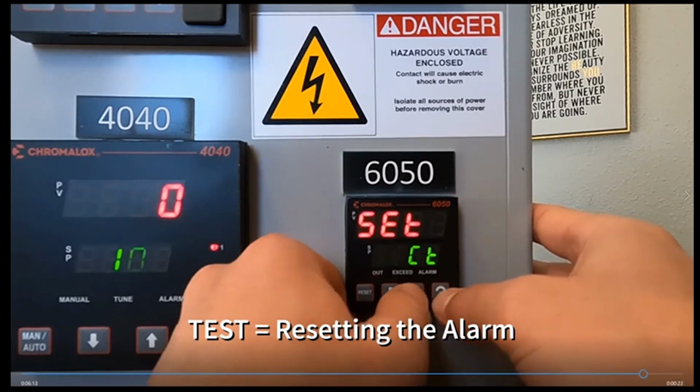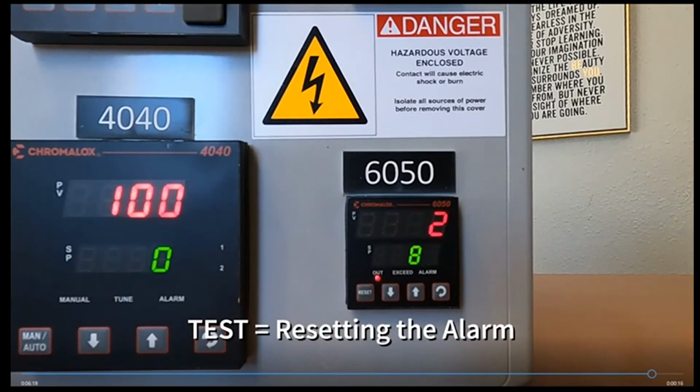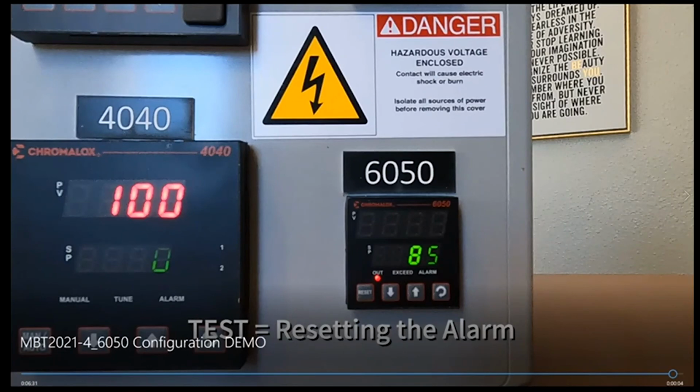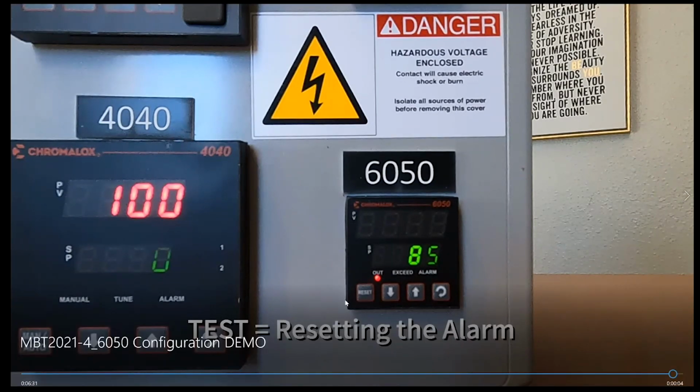Boom. But if you'll notice, the out light is still lit up. When I talked about the latching alarm earlier, this is what I was talking about: once that condition is hit, the exceed light will go out, but everything is still shut down inside the panel. This controller is connected to a contactor that's downstream of all the other SCRs. So when that contactor is shut off, everything is shut off in the process. That's what makes an overtemp different from a process controller, because it will not turn back on until a human goes in there and presses that reset button and resets the controller and says, okay, everything's good to go. We can start running again.